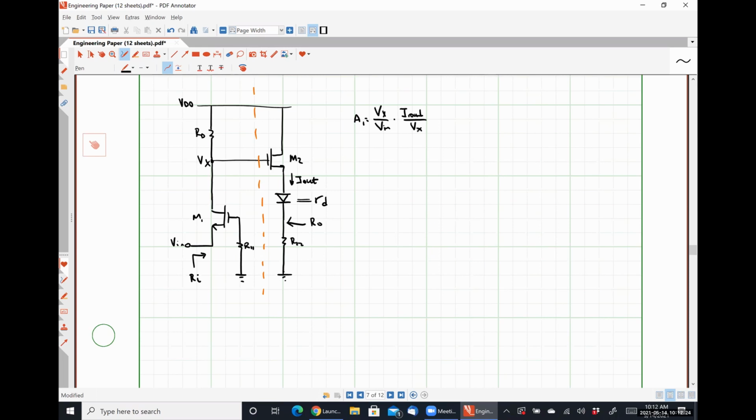Okay. So for the first stage, we see a common gate amplifier with some resistance R11 tied to the gate. What does that resistance R11 do to a common gate amplifier? Absolutely nothing. So our transfer function for our first stage should literally just be the input-output relationship for a common gate amplifier, which is, Ronnie, you nailed it on Monday. Can you tell me what it is again?